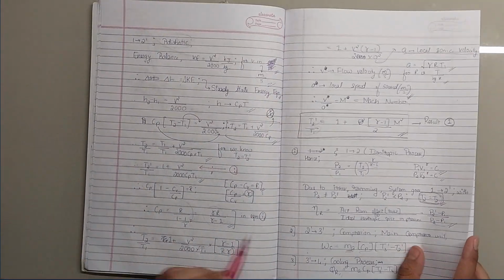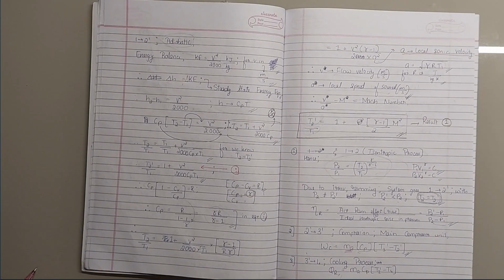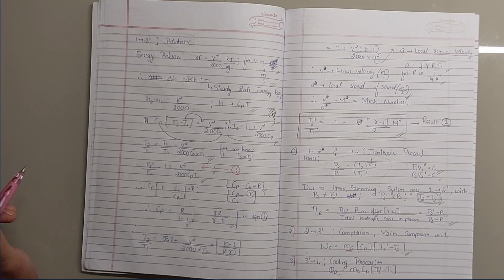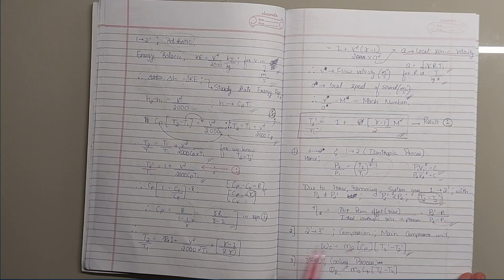Win is always the work into the compressor. We generally do not consider the turbine work because the turbine is not participating on the upper hand in the process, or also the ramming effect. The ramming effect and the turbine work are not actively taking part in the compression, so we don't consider them. They are just a shadow part, one of the parts of the refrigeration system, so they have to be there, but they are not to be considered on a first-hand basis. So we will just consider the compression work here.